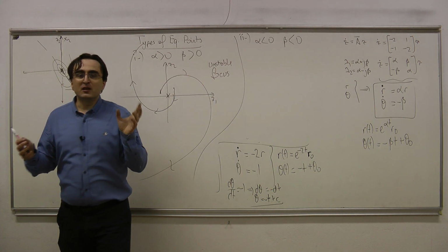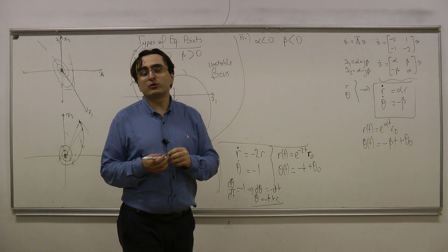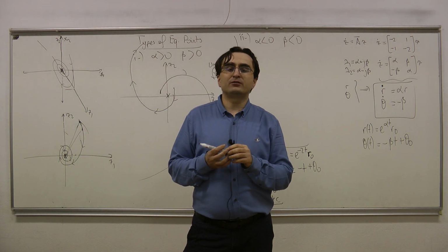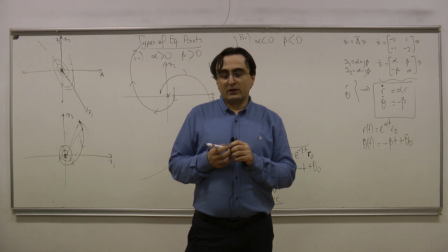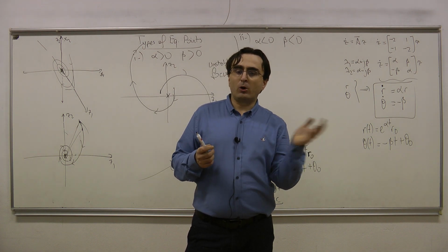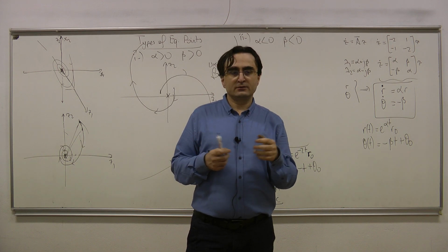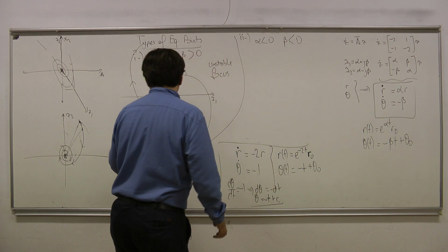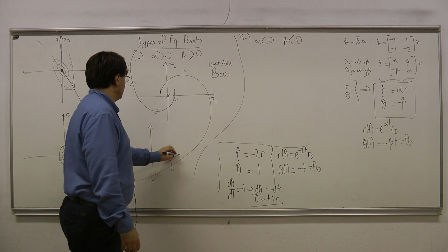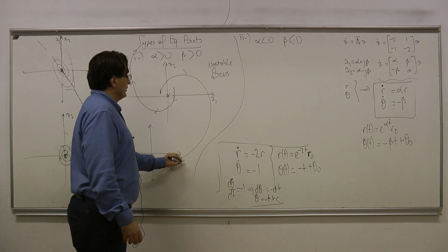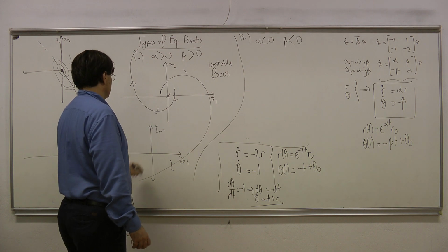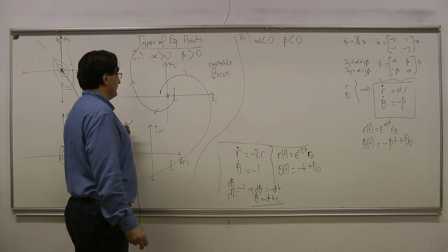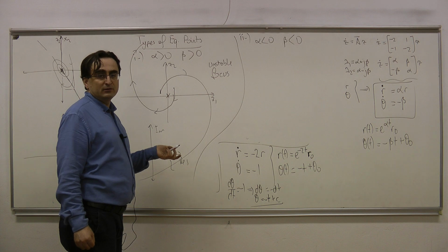So this is just similar to the poles of a linear system that you have seen in the control course EE404. Okay? Remember, if this is my complex plane, real of S, imaginary of S, if poles are here in the left half plane, then their real part is negative.